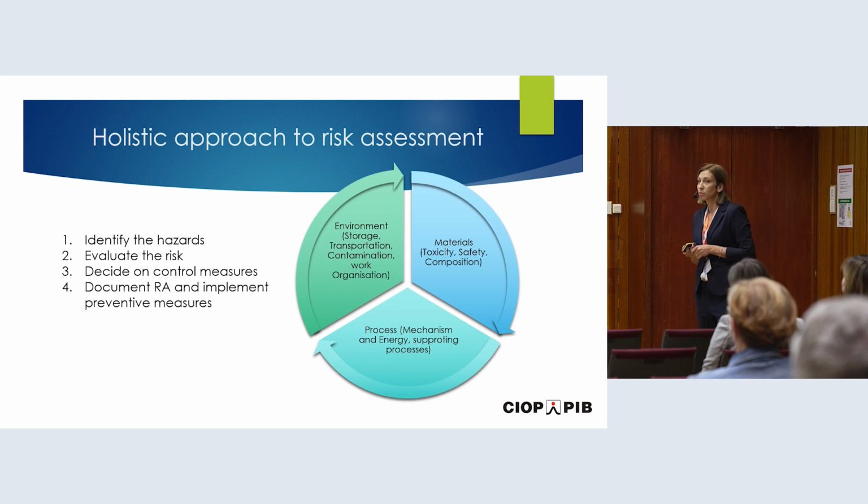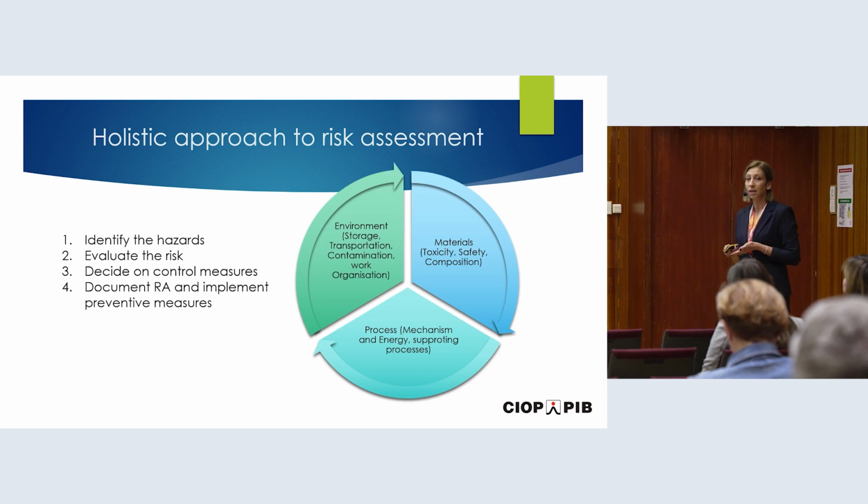In this technology, we should follow, of course, the STOP philosophy, for example, when we start with the control measures, starting from eliminating the risk if it is possible, followed by those which are really effective, like substitution of the process, substitution of the materials that are used in additive manufacturing, and also the tasks, such as technical measures, followed by organization of work and personal protective equipment.